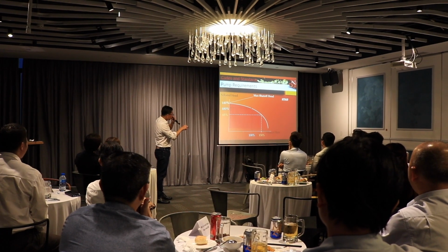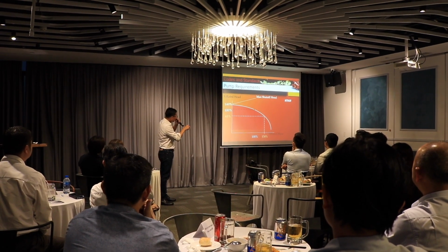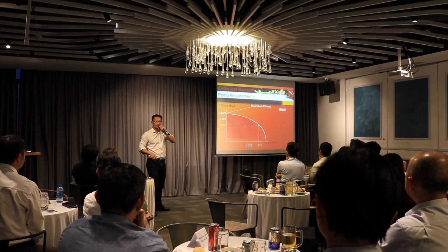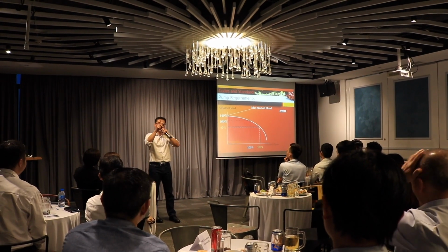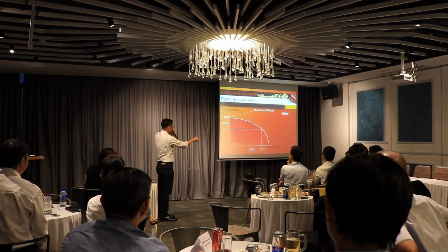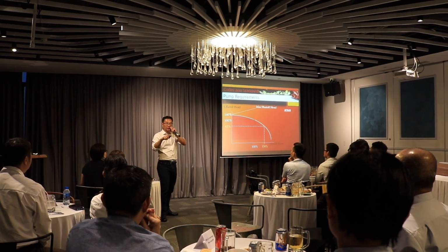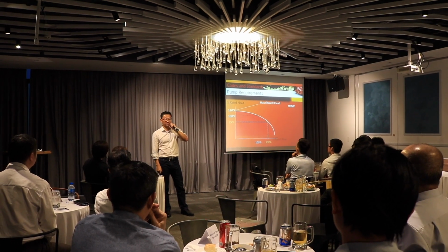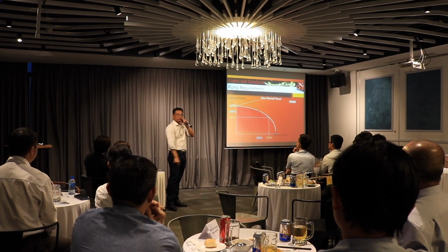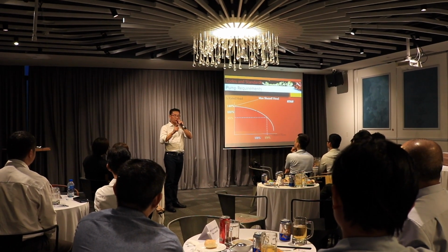Second point, the head drop at 150% should not be less than 65%. This is NFPA 20. But if you want to give UL listed, there's one more very important condition. At 150%, the suction lift must be able to do more than 3.8 meters. It's not written in NFPA 20. It is written in UL.